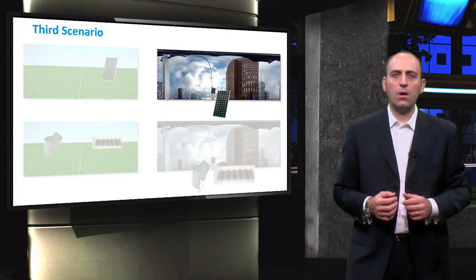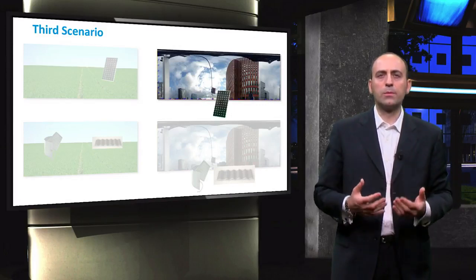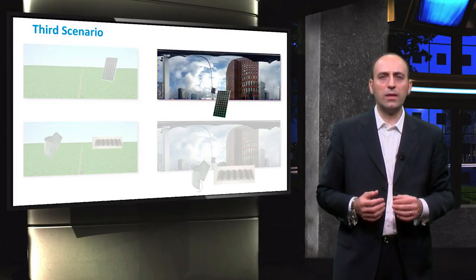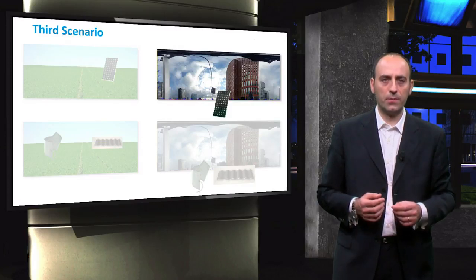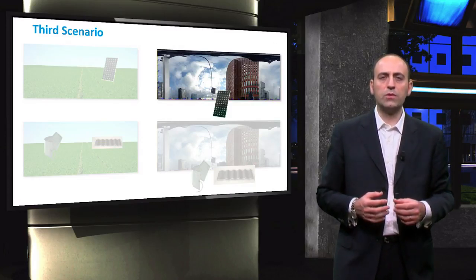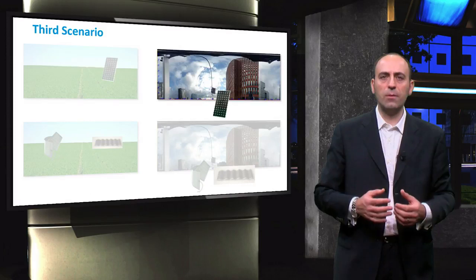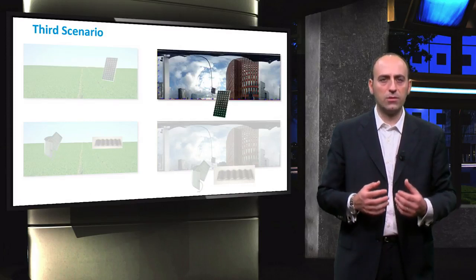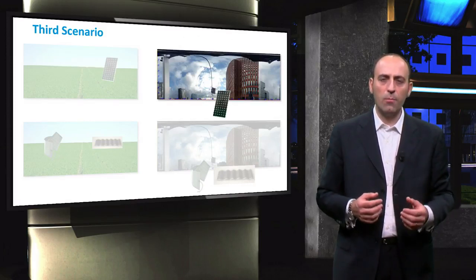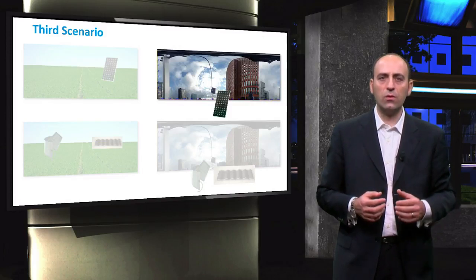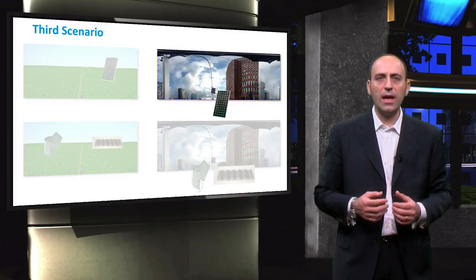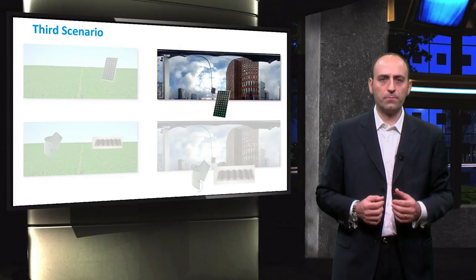Let us next move on to the third scenario, where a standard PV module along with complex horizons are considered. For this, I'm going to explain an irradiance modeling approach based on the use of LIDAR. The use of such an approach improves upon the existing options available when simulating complex surrounding environments. It combines the advantages of an on-site location survey method and a remote assessment survey.